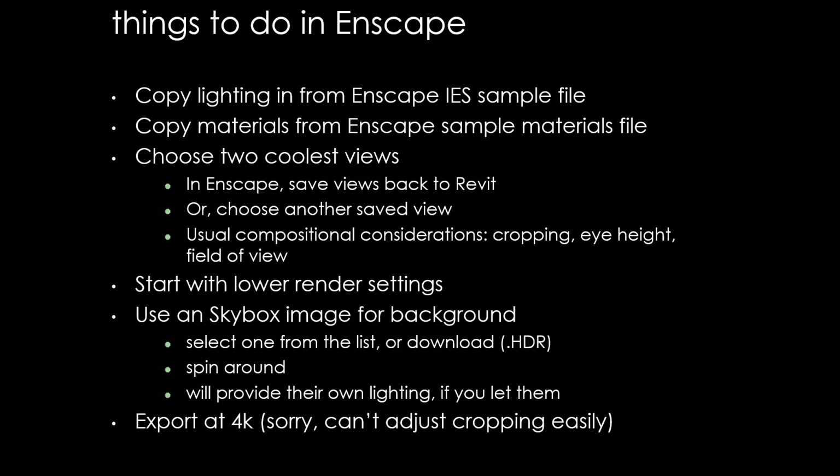Now, one more fun trick that Enscape can do is it can use what's called a skybox image. And what this is, it's basically a kind of cube-shaped image file that puts your model inside a giant cube with pictures on it. And the advantage of this, it's only slightly pronounced in still images where the exterior of the building appears natural. But for walkthrough images, it's actually really important as you walk by a window that it appear normal. Really the only way to do this is to include a skybox image. So let's take a look at that.